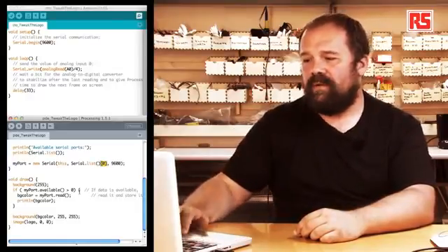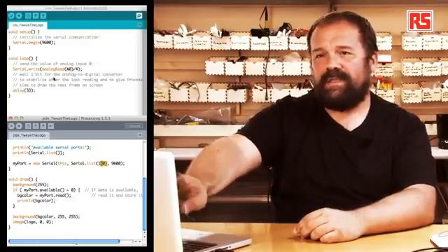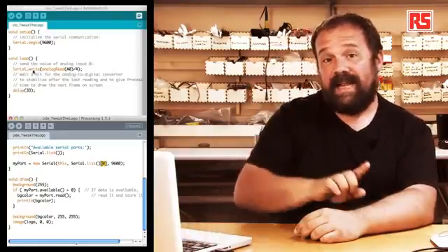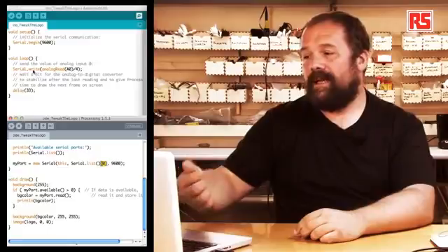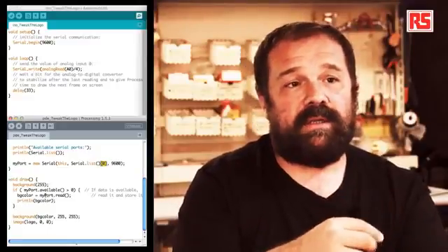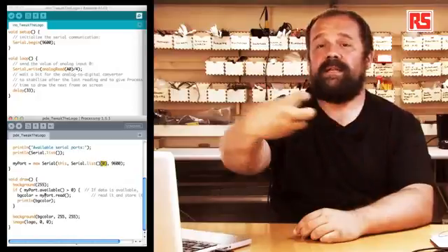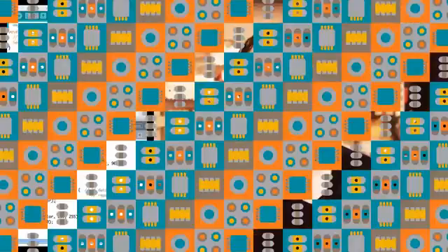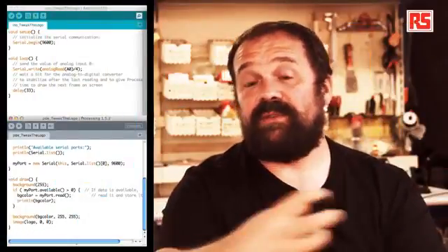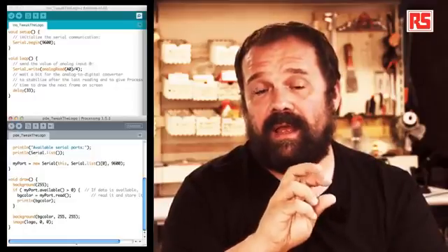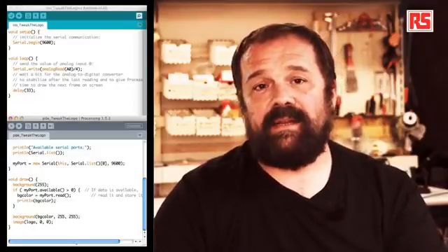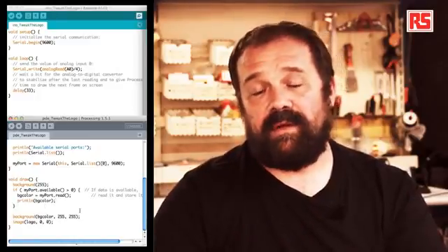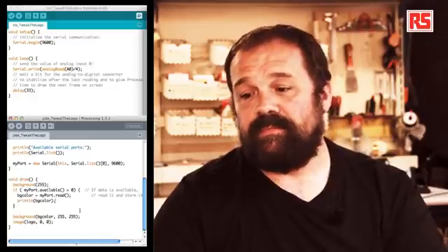So you can see now, by looking at the code side by side, on the Arduino side, we have Serial.write that sends the data. And then on the processing side, we have myPort.read that reads the same number into the bgcolor variable. After reading the value that comes from the Arduino into the bgcolor variable, we use println(bgcolor) to print the value contained inside bgcolor at the bottom of the processing IDE window.